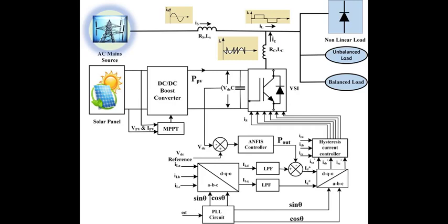Harmonic filters. Harmonics are undesirable voltage and current distortions that can occur in grid-connected systems due to nonlinear loads or power electronic converters. Harmonic filters are used to mitigate these harmonics and ensure the system's compliance with grid codes and standards. They can be passive, e.g., inductors and capacitors, or active, e.g., using power electronic devices to actively cancel out harmonics.